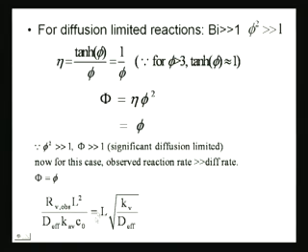And so, if we want to measure experimentally, the last thing you see on the page here where the pointer is, what my observed reaction rate is, because this is something you might want to measure, then this is how you do it. On the left hand side, you substitute the observed Thiele modulus, and on the right hand side you substitute the square root of the intrinsic Thiele modulus. One of the L's cancels out over here, and one d effective cancels out, sorry. So, you get the observed reaction rate equals the square root of kV times d effective times kV C naught over L.